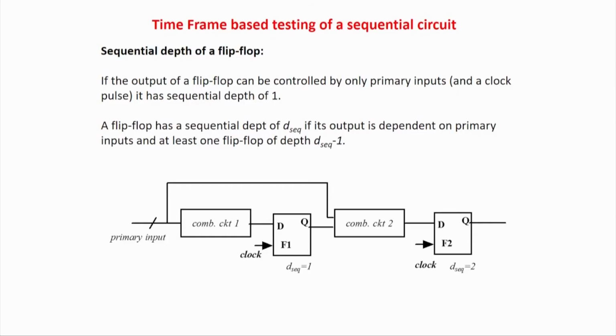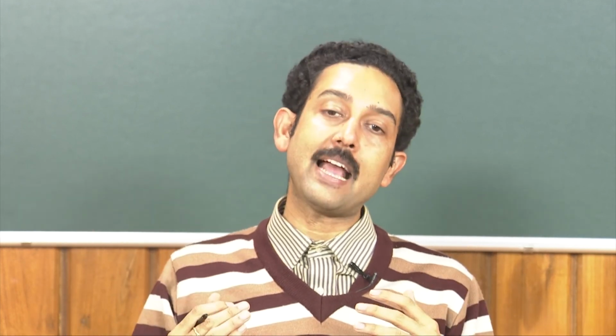While we go through these lectures, you will automatically be motivated and find out why scan chain optimization is so important, because scan chains are not only about the flip flops you put in additionally, but also about the pinouts. One extra scan chain means one additional pinout. Therefore optimization of the scan chain has a greater role to play compared to other cases like compaction circuits and decompression circuits.